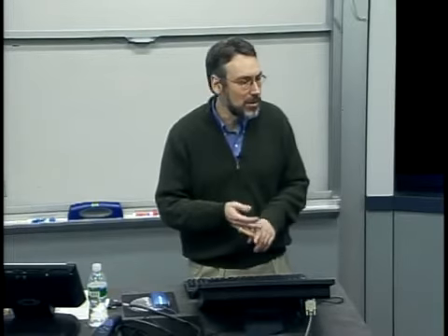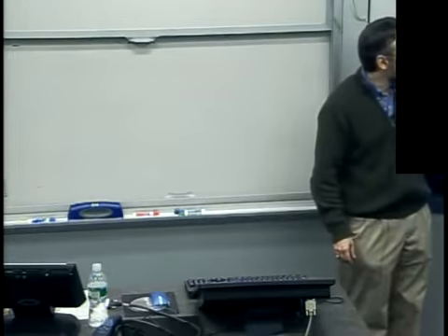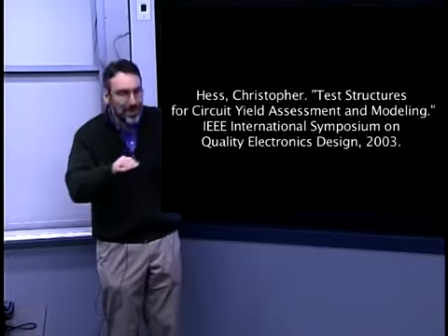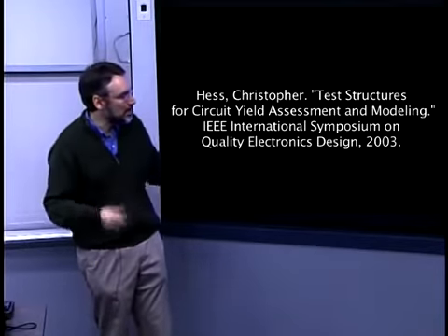Now this turns out to be still an important part of semiconductor fabrication: understanding your defect densities, defect counts, understanding what the typical sizes are, what levels of the process they come in. Are you mostly getting these in aluminum deposition? Are you mostly getting these in other etch processes?